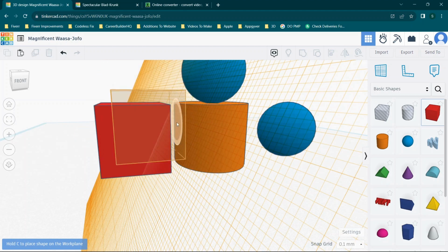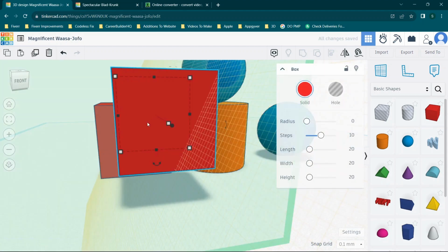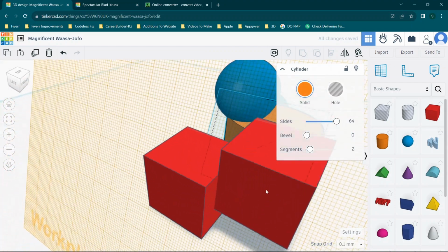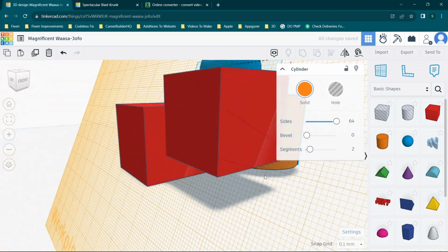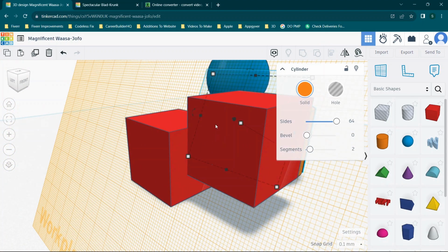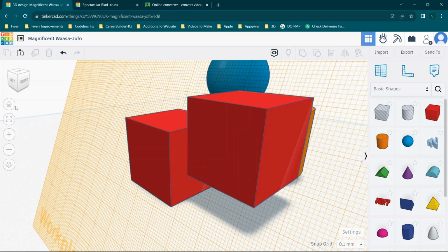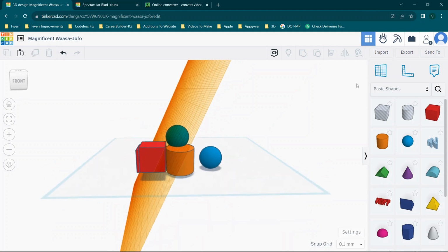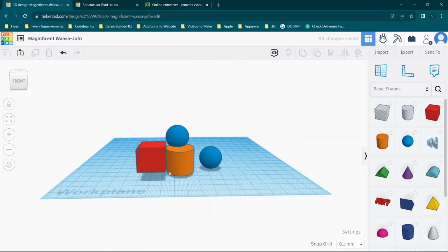And then the idea is you'll be able to place it on that plane and work with that object. So an example is if we were to go around and let's just say we place the object here, and then we can go back to our original work plane. So you have a couple of different options and ways to do that. So first up, if we hit our home button, you'll see we have our work plane that is diagonal-ish to our main plane, so to speak. And to change the plane, you can just click here and choose the new work plane. So that's really all that there is to it.